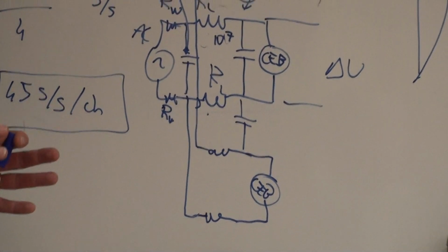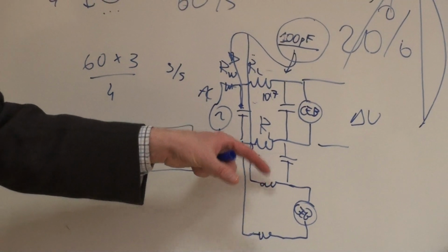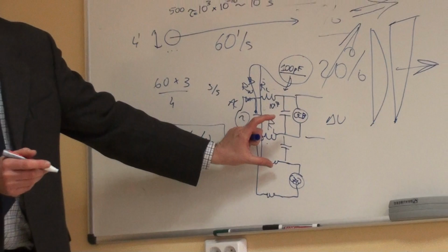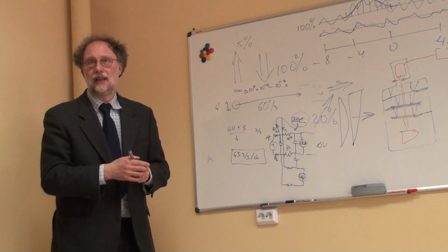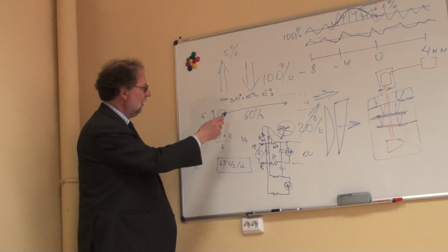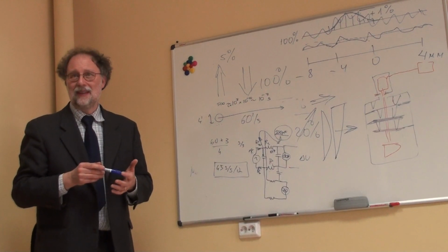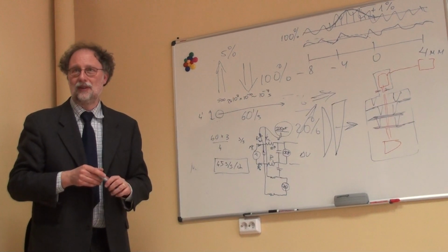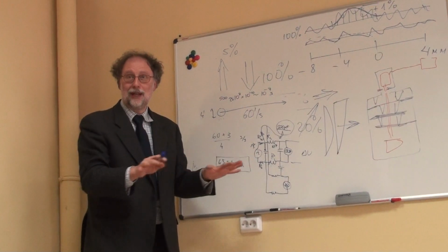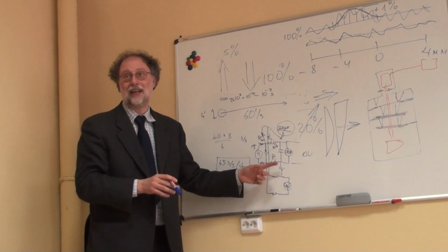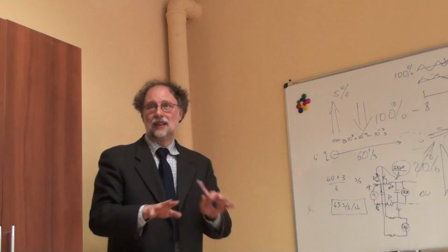So if you use high frequencies for the bias, you have intermodulation, crosstalk from channel to channel. That's why I'm saying a few hundred hertz, not more than that, to avoid these kinds of problems. But this should be checked once we have the array and we see what the stray capacitance is on the array, channel to channel.